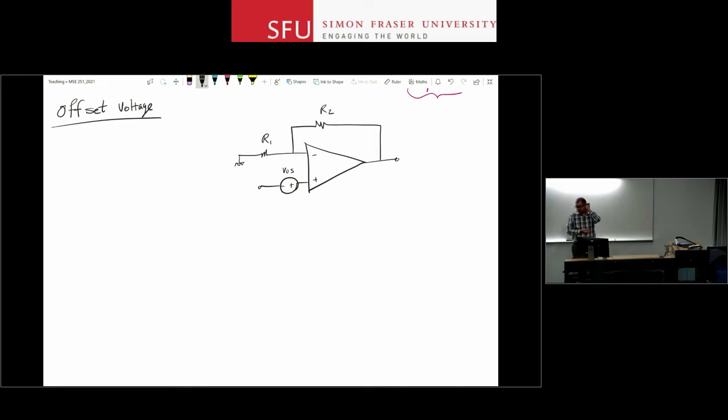The second approach to deal with the offset voltage is to just get a different op-amp. You have a ton of op-amps available to you nowadays. Each manufacturer of these integrated circuits has a library of op-amps, and especially the newer op-amps are not really that much more expensive than the old ones, but they may have a significantly smaller offset voltage. They can achieve lower offset voltage in 2 ways. In one situation, they get a better hang on the manufacturing techniques, so they got rid of all those randomness and tolerances, so they get a better offset at the output.